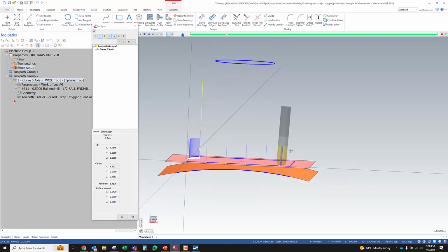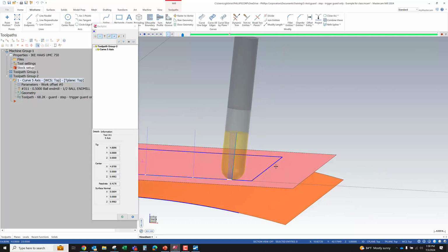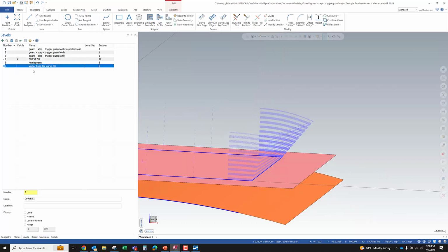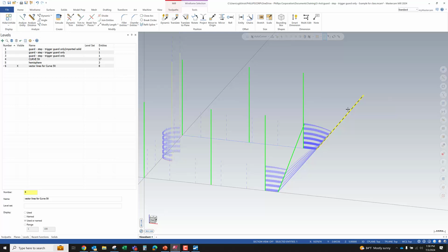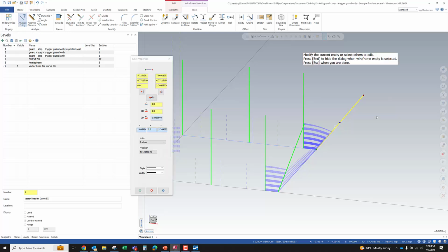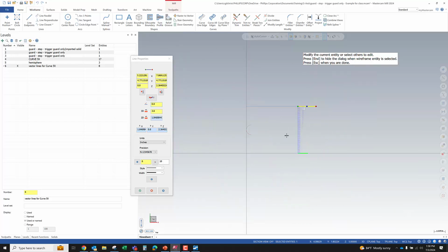So you just change the angle by analyzing it? Yes. How long has that been a thing? It's been a thing for a long time in Mastercam, but there are some caveats to it. So, for example, if I go back to levels and I look at my vector line and I analyze this angle right now, it tells me it's 0 because my plane is set to top.